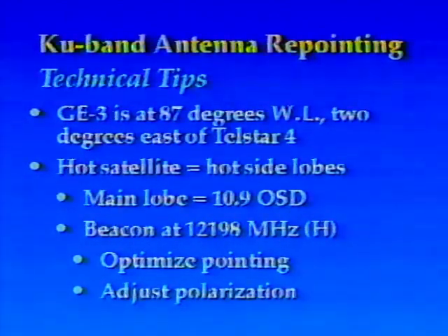There is a beacon at 12198 megahertz. You can use that beacon to optimize both your pointing and polarization. But again, look for that 10.9 OSD reading to make sure that you're really on the center lobe of the satellite.